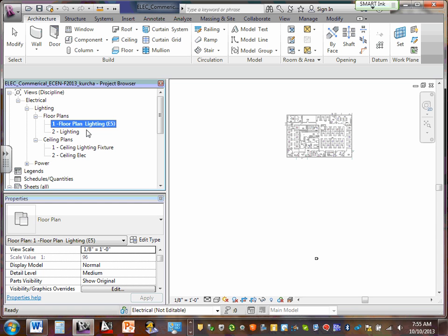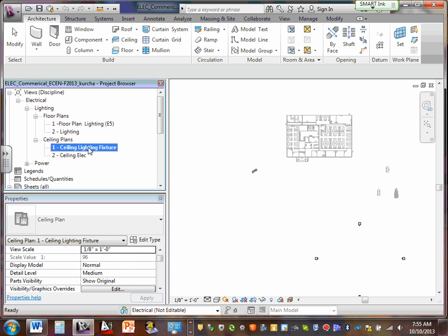Anything in the ceiling, we're going to drop in the ceiling. Just drop. What's drop? Grab the family, bam, bam, bam, put them there. Don't touch, don't circuit, don't loop, don't do anything. Drop them. When you see them there, move back into this floor plan. Go put your switches. You need switches there in the walls. Put your switches, tag them, circuit them. I'm probably not making sense, but you're going to see that when we go. So ceiling only for dropping fixtures. Okay, so that's the first one.